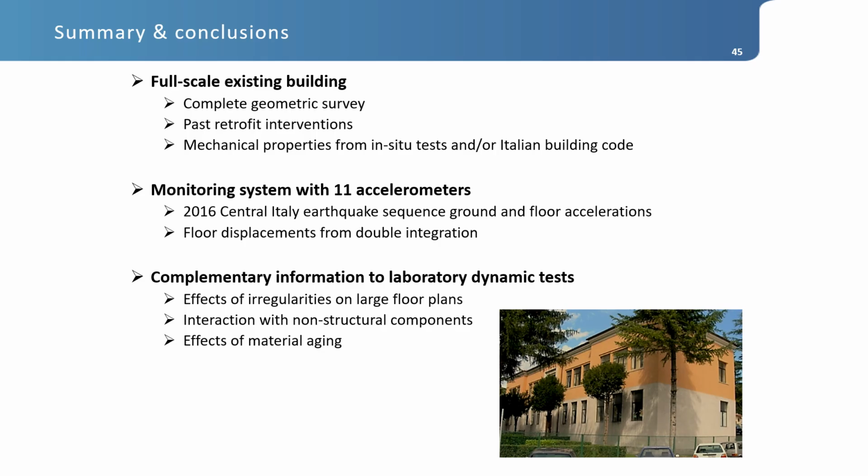These 11 accelerometers of the monitoring system were acting during the 2016 Central Italy earthquake sequence, and they recorded ground and floor acceleration in different points, and from double integration we could also derive the floor displacement.